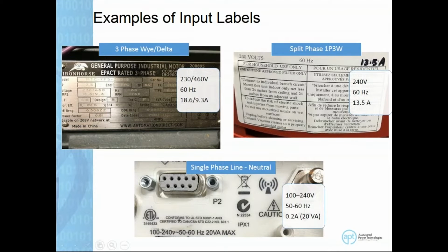One thing I will tell you is that in a household setting, the limitation of power comes from the power breaker. The breaker is a 15 amp breaker, and some of the National Fire Code would not allow you to run more than 80% of the capacity, so 80% of 15 amps. So the max current you could get out of a household setting could be around 12 amps.